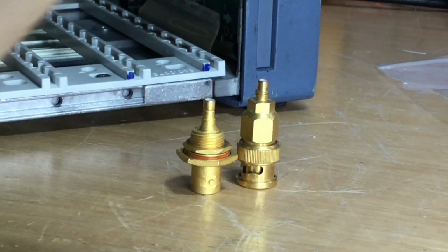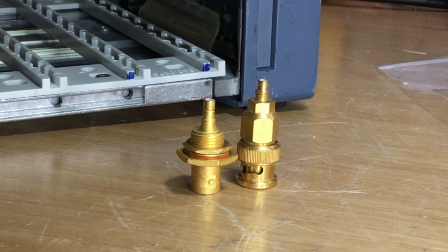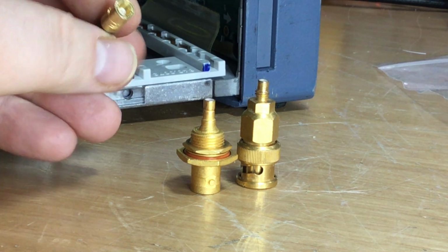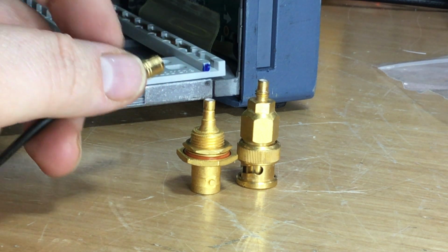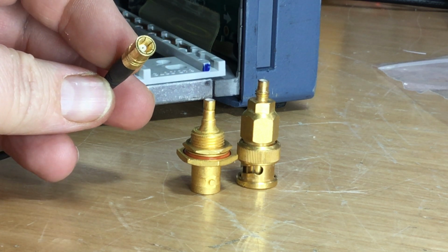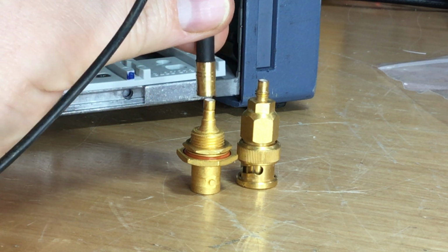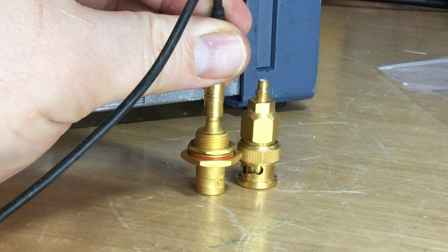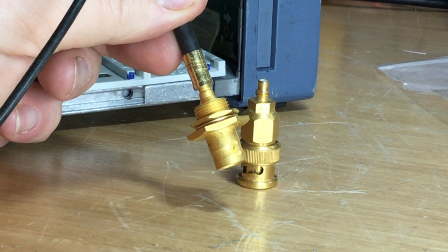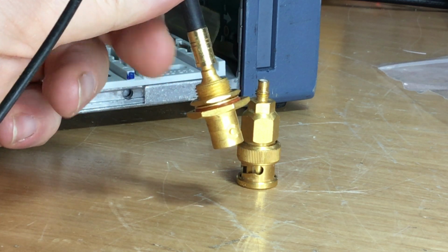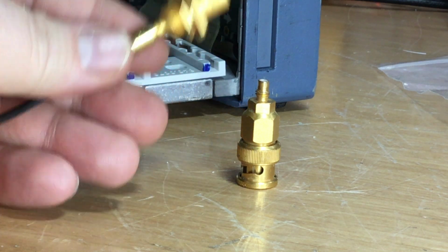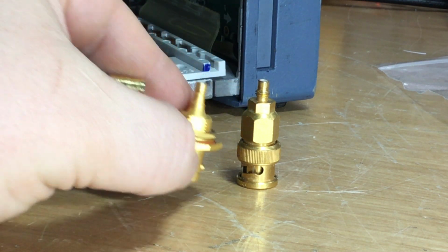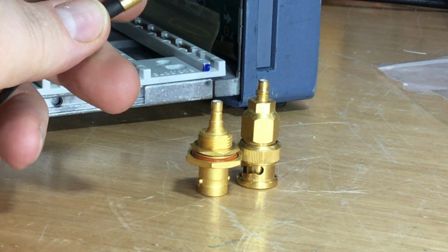Now what's interesting about these connectors is that I've often seen engineers over the years try and drive an SMB onto an SMC, which I'll show you. But this SMB here, which is what we find on these modules in this radio test set, is an SMB plug. So that plugs directly on, it just pushes on and it clicks, and then it's on, and that's home. And as you see, there isn't a nut on this, so it's not meant to be twisted and connected that way. It's just meant to be a push fit, so then we can remove that from that adapter.